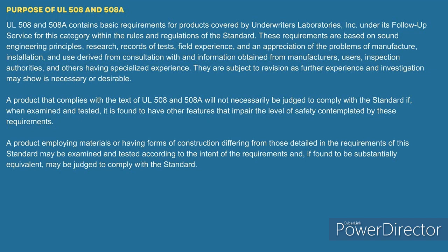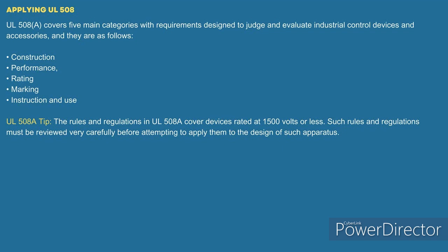Yeah, Andrew, a good rule of thumb that I've learned, and James probably got me on this a bunch of times, is that you don't need the working clearance if it's not likely to be worked on energized. And we ran into this with a gear section that was 4160, and the 70E teacher was like, "Are you going to take those screws off unless you're suited up?"